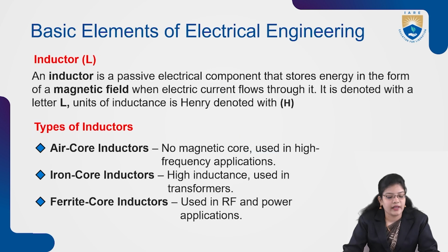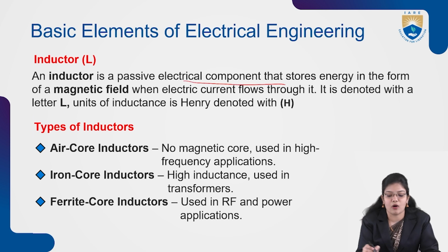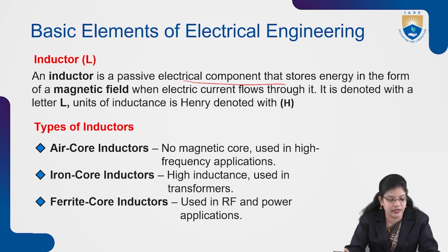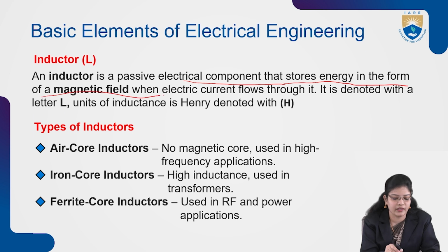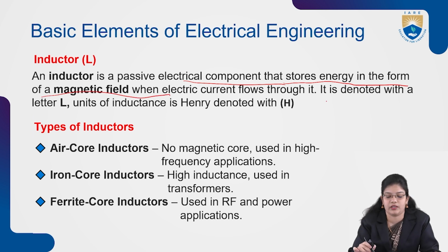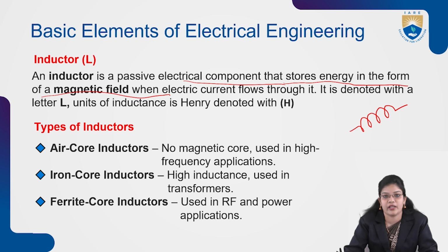Next one is the inductor. An inductor is a passive electric component that stores energy in the form of a magnetic field when electric current flows through it. It is denoted with the letter L. The unit of inductance is the henry. The symbol of the inductor is drawn in this way. As I have already mentioned for the resistance, it will not have any polarities. Depending upon the direction of the current, we can denote it as positive or negative.